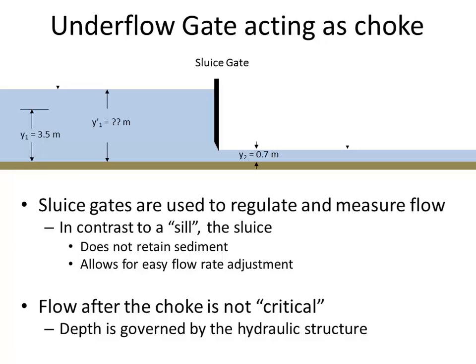Do we need to assess the flow regime to find out critical versus subcritical? Previously, when we were looking at 1 versus 2 for a channel getting narrower or a step up, we would choose the route associated with the regime: if there is subcritical at 1, then there will be subcritical at 2. So should we apply the same logic here? Should we say if there is supercritical at 2, that must mean there's going to be supercritical at 1 and vice versa? Why not? Because the water level has to rise to keep up the energy.